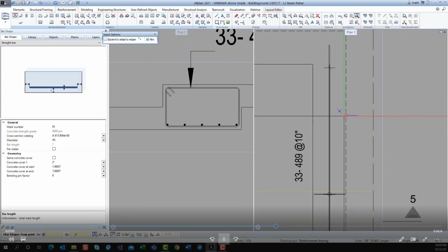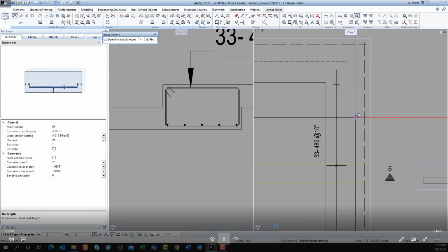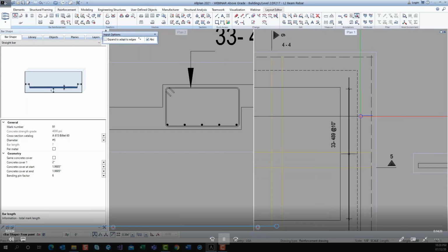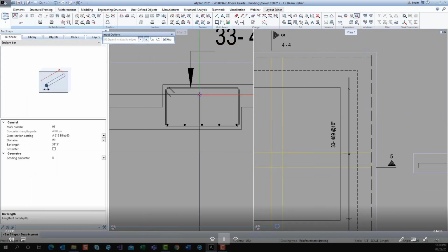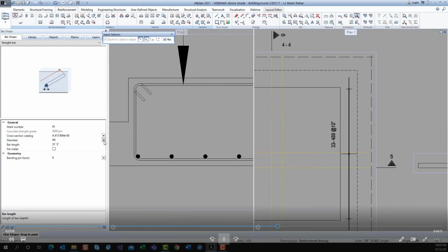Now what I'm going to do is place the top bars in this beam with the same functionality. I'm going to place it as a section, change the size, and paste in the number again. I don't have to remeasure because I didn't copy anything else. Paste it in and put in a different calculation, 2 times. This one happens to be, I believe I did 30 inches. Now it's a 32'5" bar.